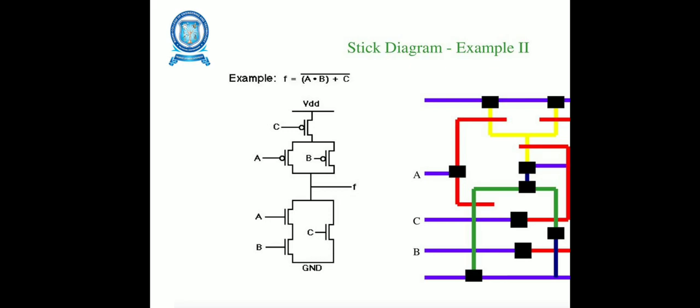This prevents shorting and keeps the contact from slipping out of the area to be contacted. When no separation is specified, wires can overlap or cross, so the metal is not constrained by any other layer. For CMOS, note that the N diffusion wires can only exist inside, and P diffusion wires will exist outside the P well. The main thing to be noticed is these design rules.